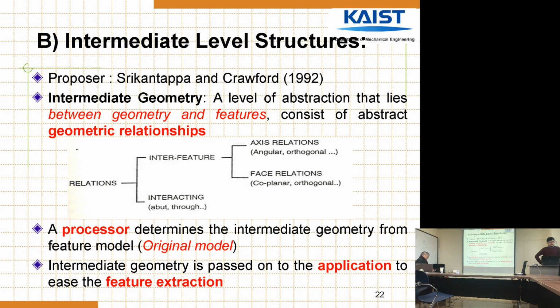So why relationships? Because let's say if one design feature is to be used by 10 different machining systems, instead of adding the detailed information of those 10 different machining features, it is better to add relations which can be used to get that information, something like expressions or equations.